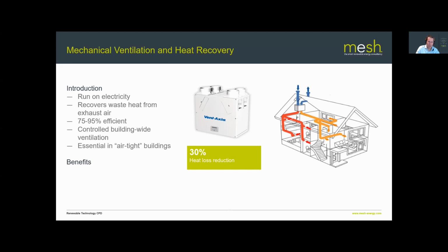We would be encouraging architects to think about, especially on new builds, trying to design air tightness down to sort of 1. So you're really getting super airtight buildings.